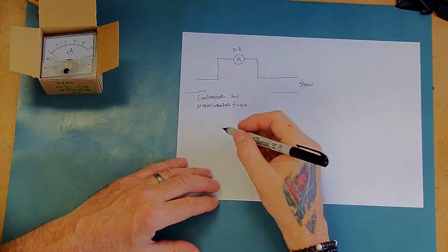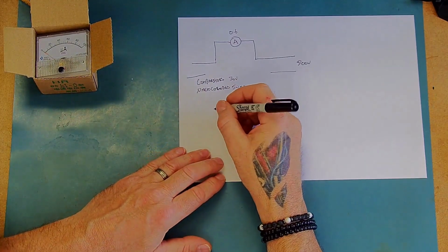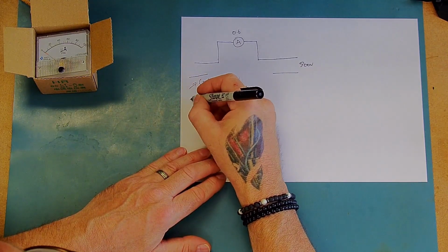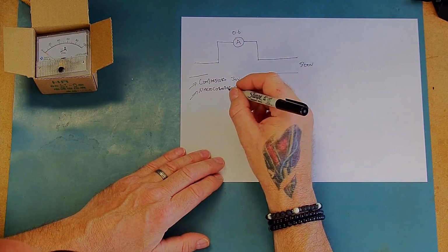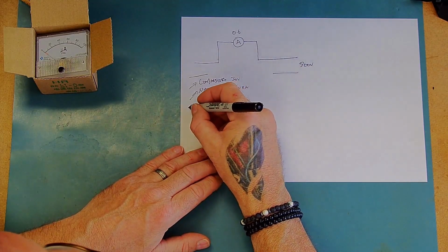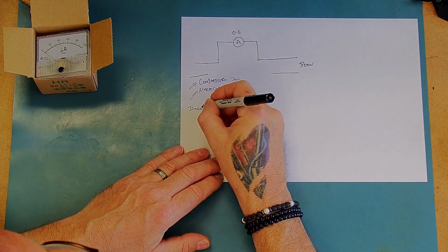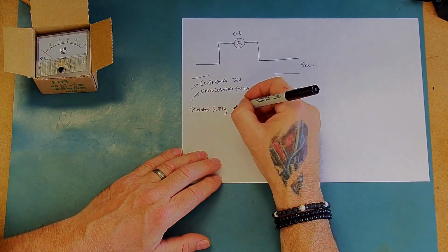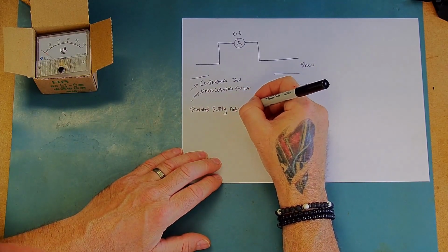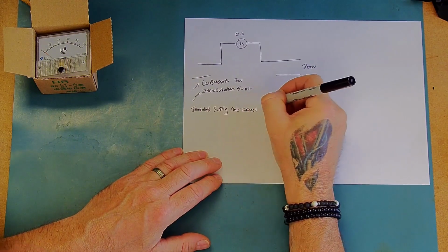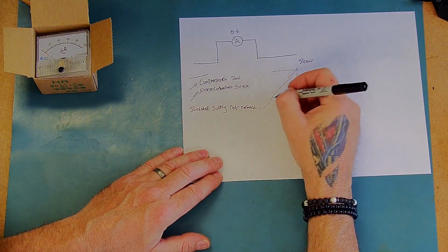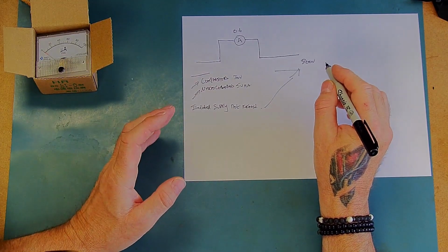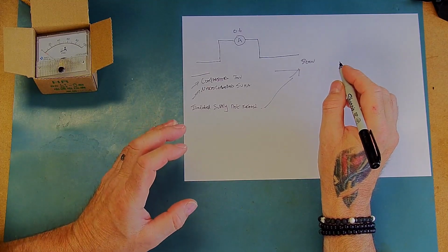And what that means basically is that any supply voltages to the comparators and the microcontrollers potentially are going to need to come from an isolated supply, which is then not referenced to the ground potential of the 800 volts. So I've got to have a little bit of a think about how I'm actually going to achieve that.